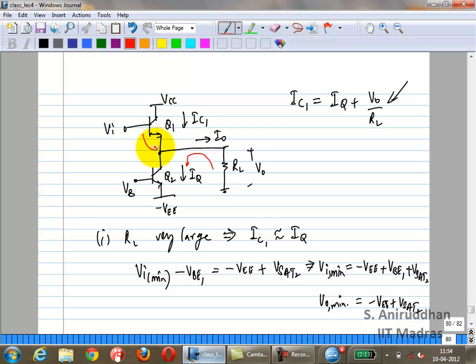If you apply a small signal at the input plus a bias, at the output, you will get bias minus VBE and the small signal around that of gain 1. Okay, but right now we are not even talking about the signal. We are talking just the DC characteristics. Okay, we will find out how to figure out the signal characteristics from the DC characteristics. Right? I am sure you have done that before, but we will do that for all three cases, class A, class B and class C.